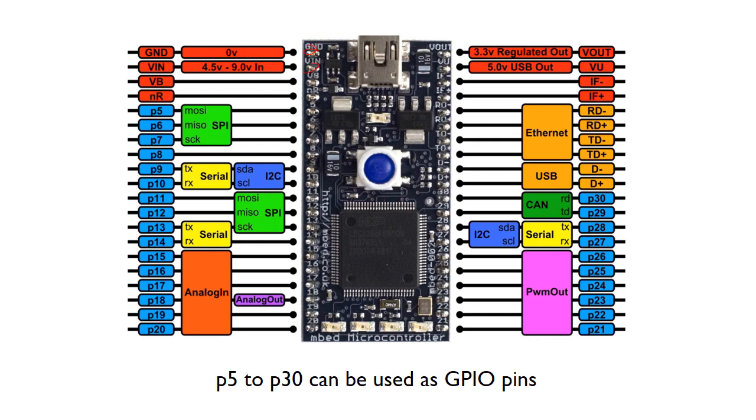All these silver things here are actually pins which allow us to plug this into a breadboard. So this development board plugs into a breadboard, and if you look closely, there are various tracks on the PCB, so you'll be able to see that the different pins are routed to some of these pins on here, for example. By plugging into the breadboard, we can connect wires to these pins here, and it will give us access to the actual pins on the microcontroller.